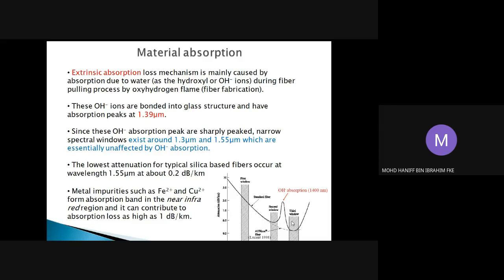That is why our interest is to work at these particular wavelengths, at 1.3 and 1.55, due to this effect: number 1, very small absorption, number 2, very small scattering, and number 3, very small hydroxyl absorption loss.